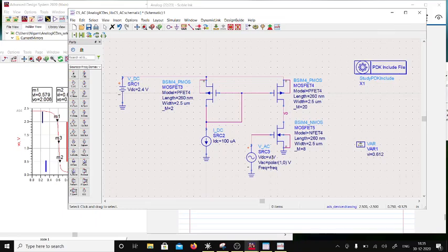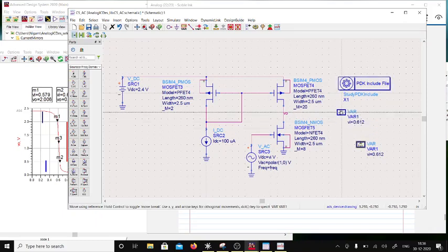I am having VI as the DC voltage, and then I am swinging 1 volt at the input. Because it's an AC simulation, it's okay. The output can be around 1000 volts irrespective of supply. Then I will be able to get the gain.